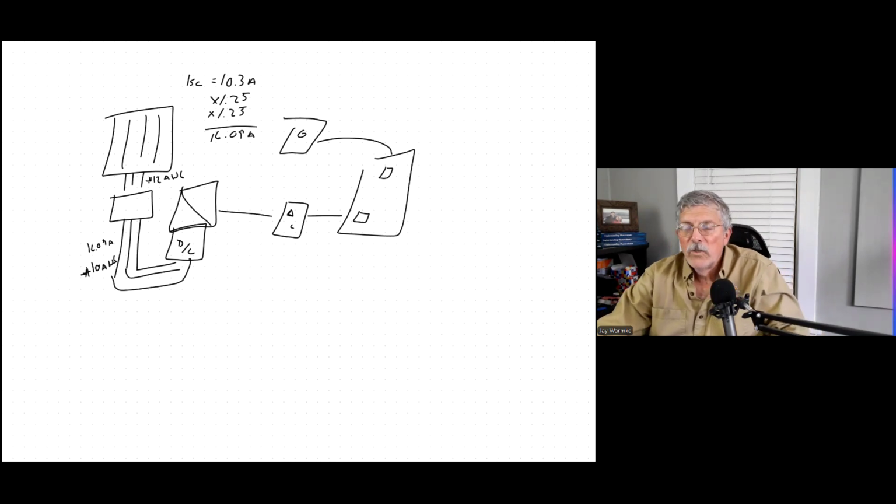If it's lying on the roof, you have to add 33 degrees Celsius. I think that's right. I'm going by memory here. I'm just double checking, reading through. Oh, wires and conduit. Yeah, 33 degrees.